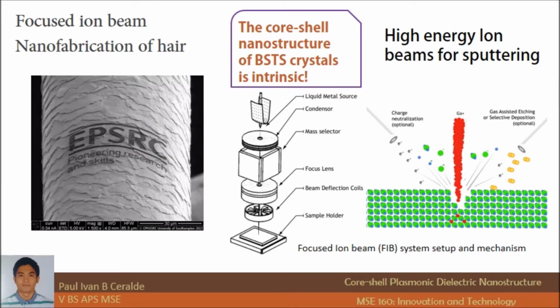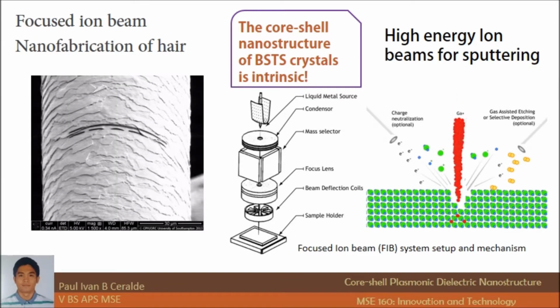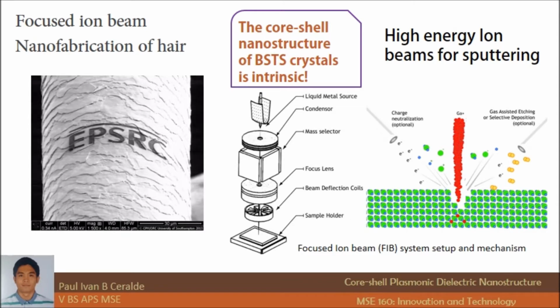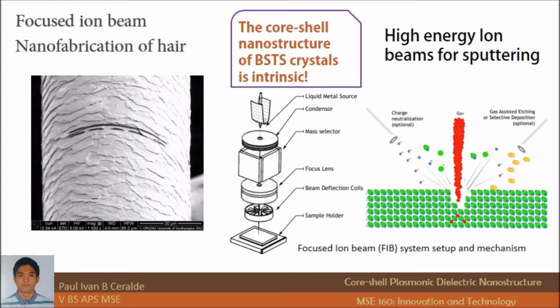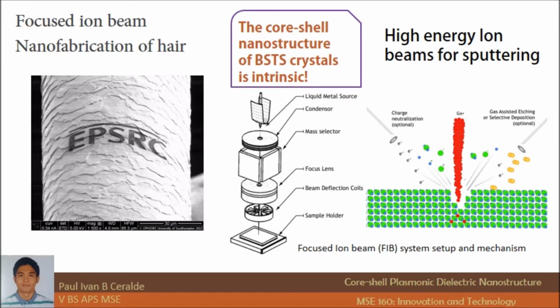Essentially, a high-energy gallium ion beam having positive charge hits the material surface to displace a certain level of the material's molecules. This method is commonly used for nano-etching as shown on the left. The conical patterns were administered using two cross gratings with variant periods to manipulate the topography.